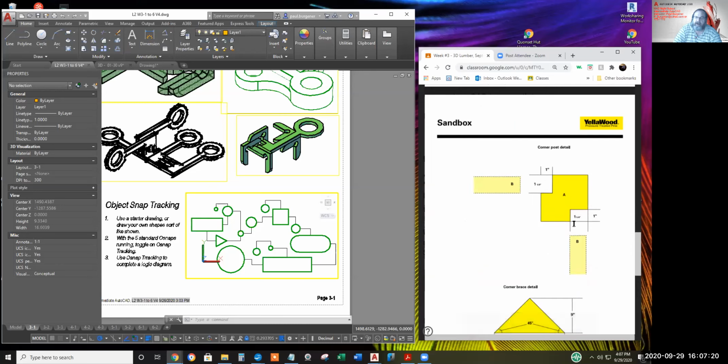Well, it occurred to me it might be a step easier if we just draw this shape with the polyline command or PEDIT join it into a polyline rather than making it a block and then subtracting out 2 blocks. With me, might be repetition to demonstrate the subtract command again.